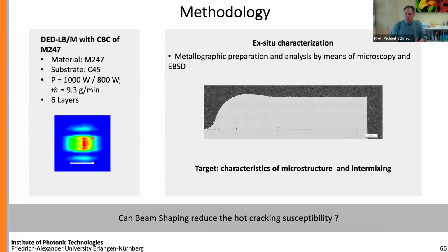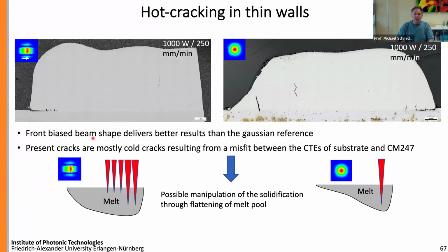The shape of the molten pool plays a big role in bringing in micro cracks, hot cracking, which in a DED part might lead to larger cracks and even come together and crack through the whole part. So we compared this, and this is the pictogram that shows the intensity distribution. To the right side is the feed speed with a ring shape, or in this case with a conventional defocus.